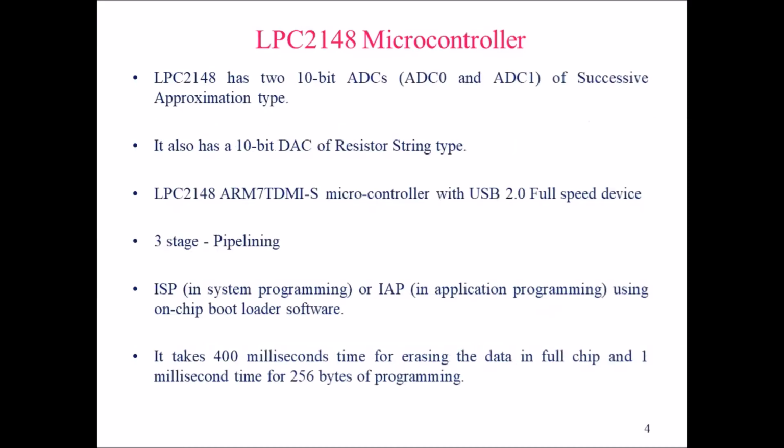LPC2148 has two 10-bit ADCs, called ADC0 and ADC1, of successive approximation type. ADC is an analog to digital converter. If we are executing programs related to electronics and want to convert analog data into digital data, we make use of this ADC.